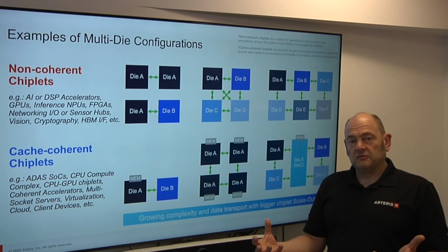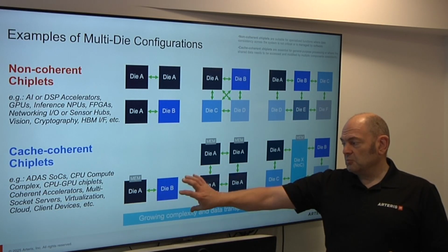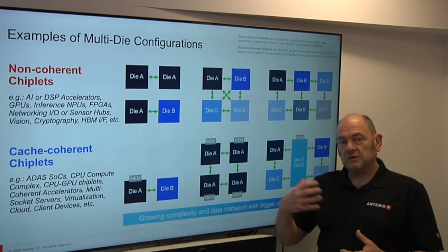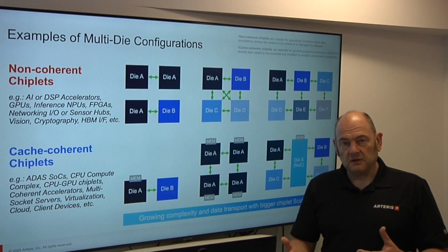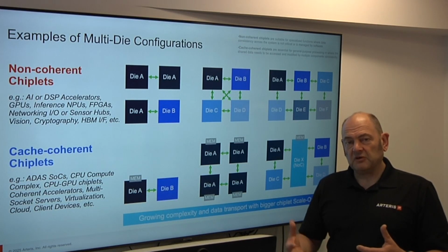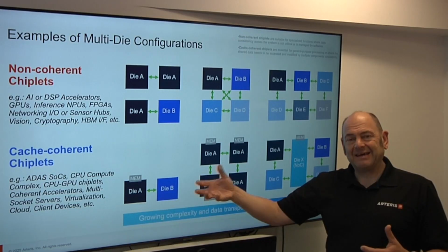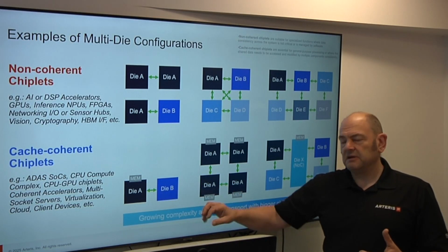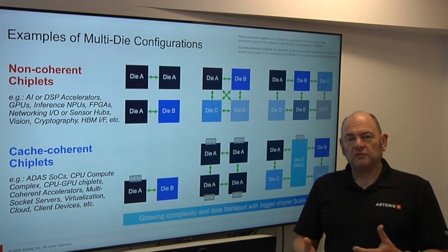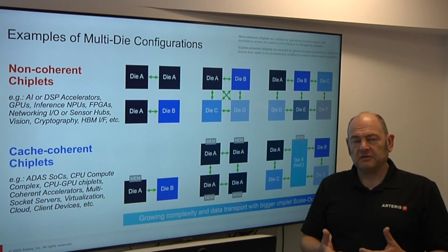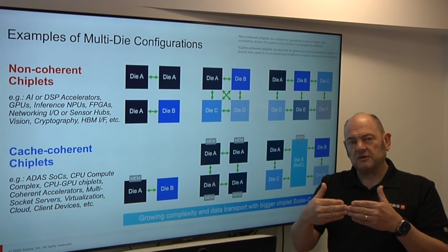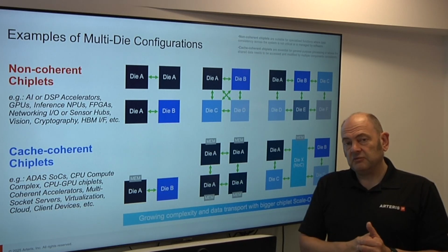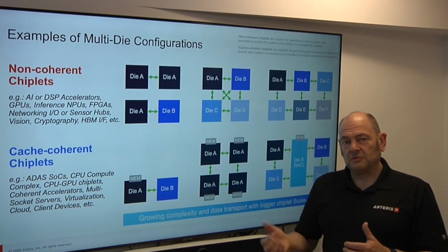That handshaking is obviously handled between the two. But because we've got different dies, we can upgrade one or the other at a different rate. So if there's an error or an issue or problems you have with a particular die, that can be upgraded independently. The first die, all the software remains unchanged, the functionality remains unchanged. All you're doing is just changing that connection interface. So that actually saves time to market when you're doing derivative or upgraded designs.